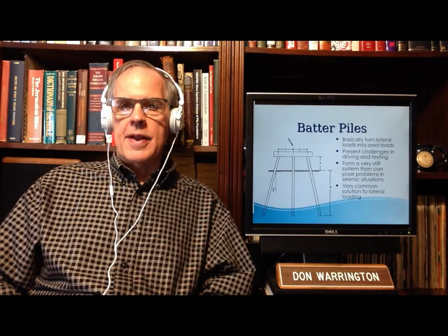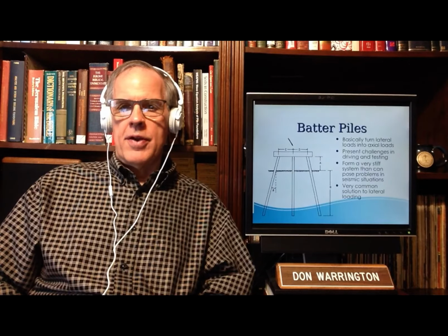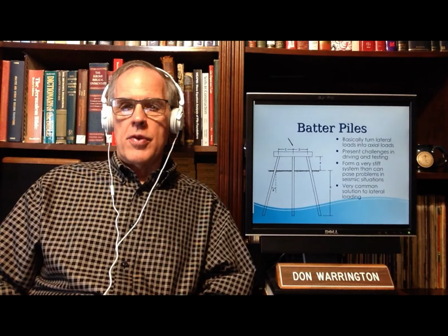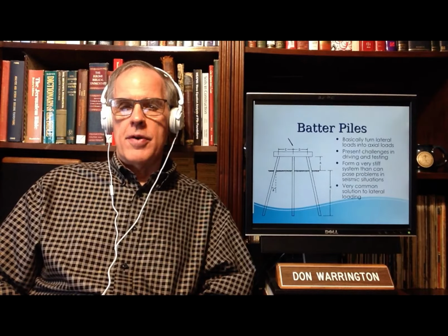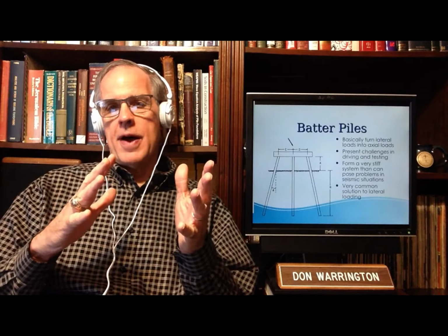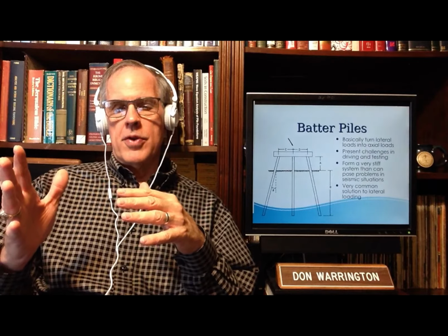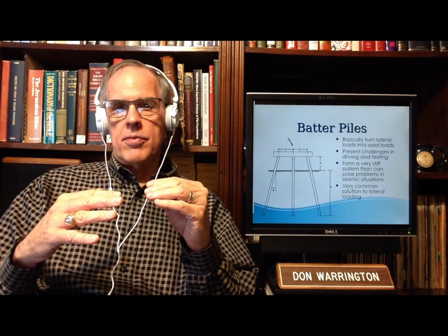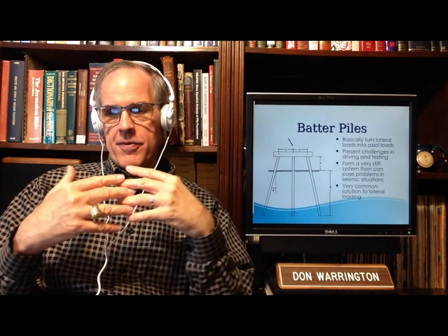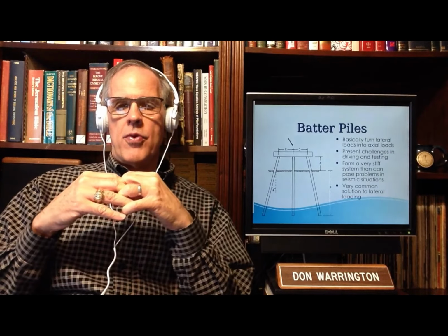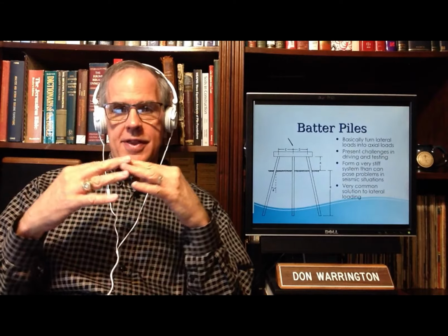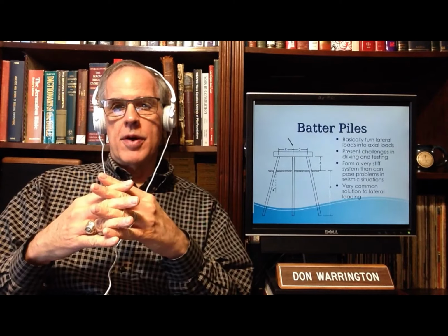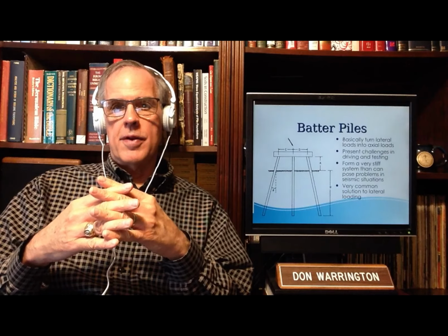Basically the idea is if you put the pile at an angle and you subject it to a horizontal load, then that load will have a horizontal and vertical component, and it turns a lateral load into an axial load and gets rid of the beam effects, at least to some degree. For many years, this was the method of dealing with lateral loads in piles. And you see them quite a bit on bridges and that sort of thing.